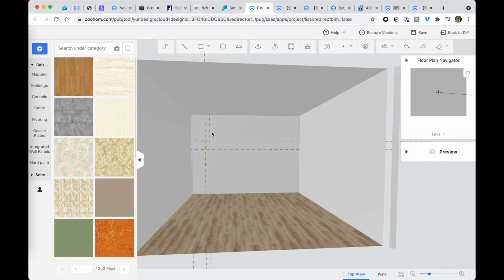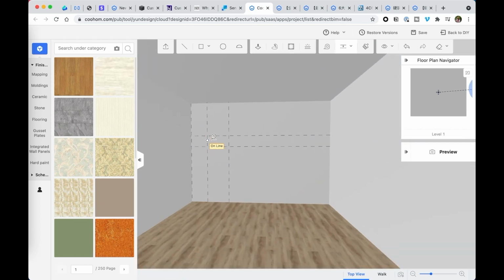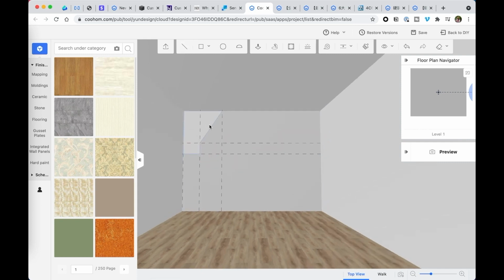Okay, let's make these reference lines a slightly more dramatic. Let's add another one here. Let's say 24 inches. Okay. And then I'm going to use my line tool to connect this point first. So this is the profile that we wanted to loft, right?